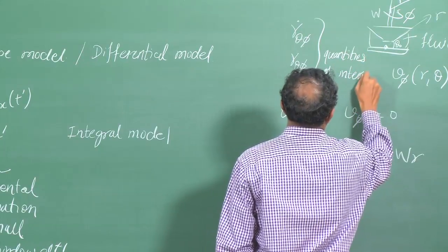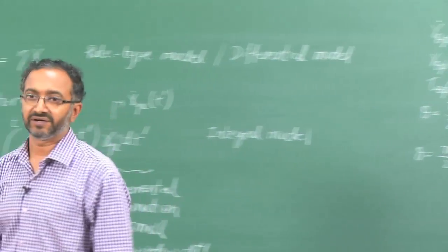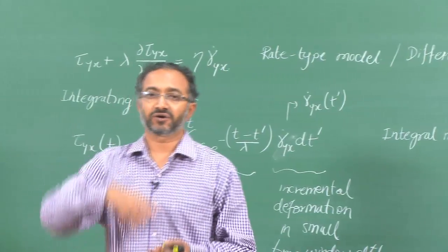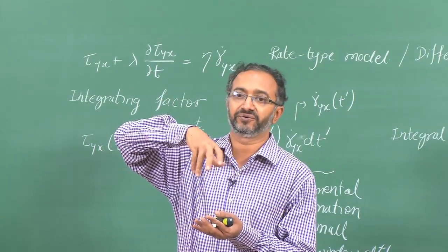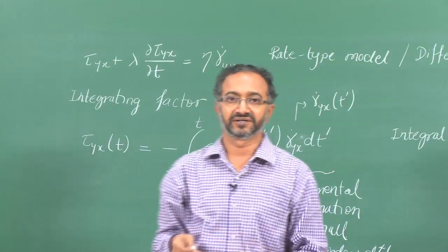So any of these could be controlled and varied sinusoidally. So, if we have the top cone oscillating, basically we are doing this, or we could say that we will control the torque which is there on the top cone, and we can say that it goes to maximum, then it reverses, goes to the negative maximum, and then again goes like this. So, that is oscillatory shear.